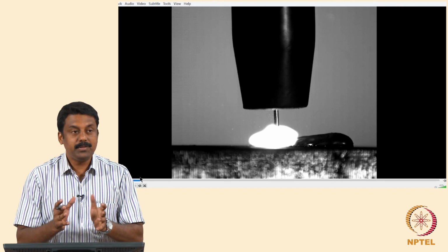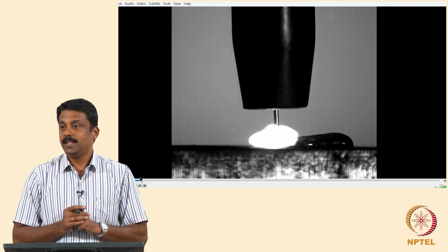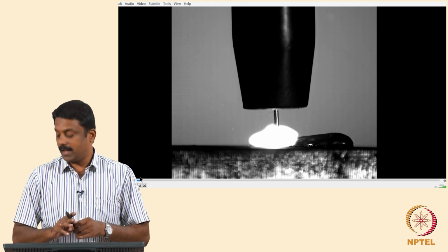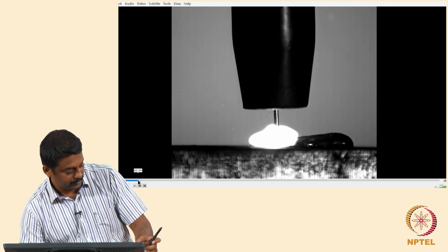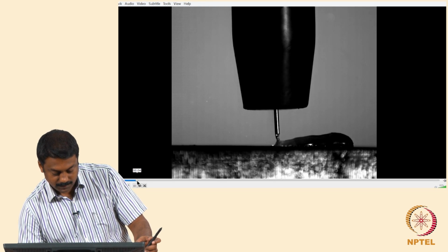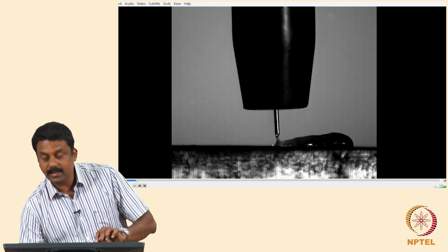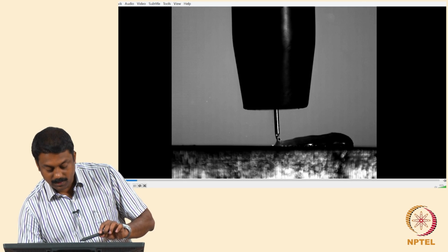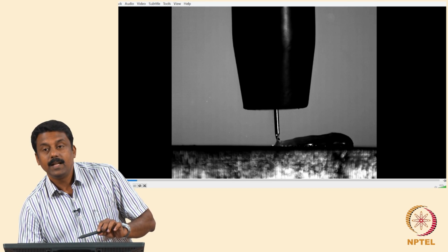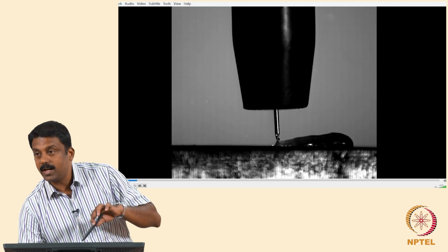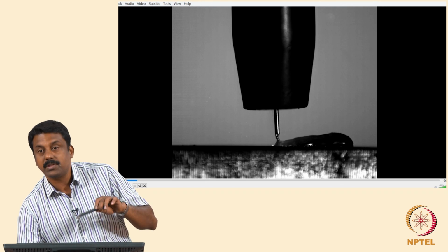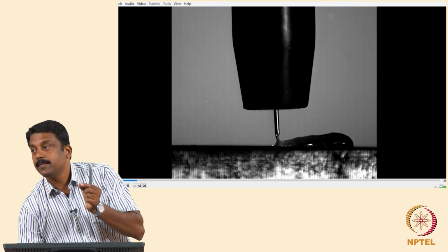Okay. So what happens if you keep on passing the current? Then you will have an explosion. If the current is passed continuously, suppose an equal amount of current is passed like an arcing current, and you have a very small area neck forming when you are retracting or doing a short circuiting, and you have an enormous amount of Lorentz force concentrating on a very tiny neck.